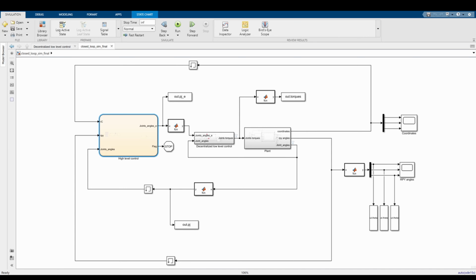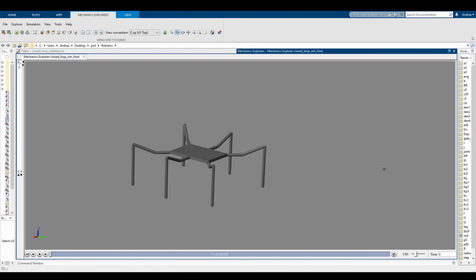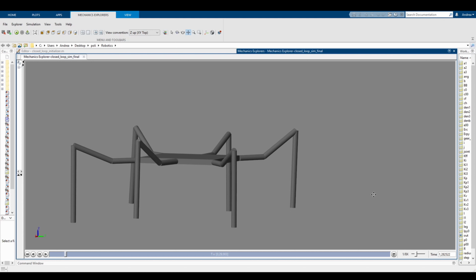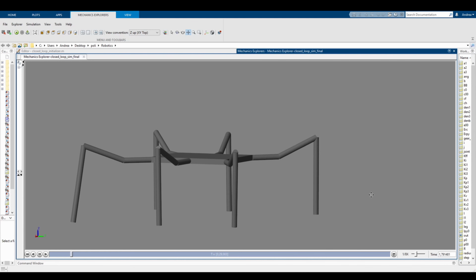To implement the trajectory planning algorithm, Simulink, and in particular Stateflow, have been employed. Given the expected pose of the hexapod, its inverse kinematics can be used to determine the associated joint angles, which in turn can be used to compute the polynomial trajectories in the joint space. In order to do this, a default configuration for the legs has to be defined, so that at each step, 3 of them are raised and moved to such a configuration, while the others keep their ends in place, ready to be lifted in the following steps.